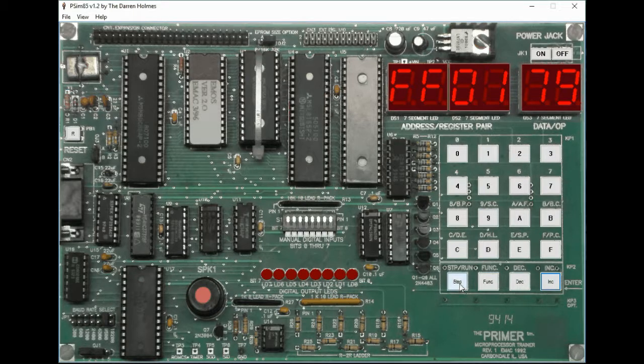So the first step, A equals C, so function AF, and we can see that A equals 0, 2. The next step, A equals A plus E, so checking the accumulator, function AF, we can see that we have 0, 1 in the accumulator, and the auxiliary carry bit and the carry bit are both set.